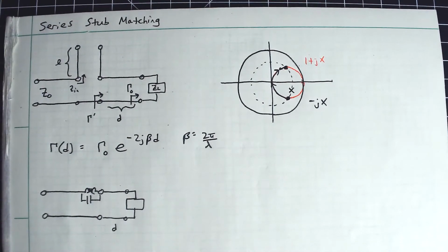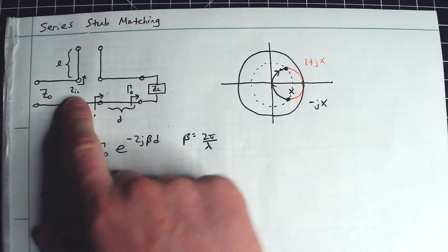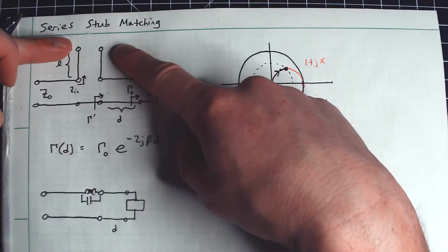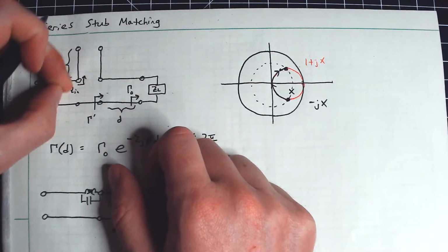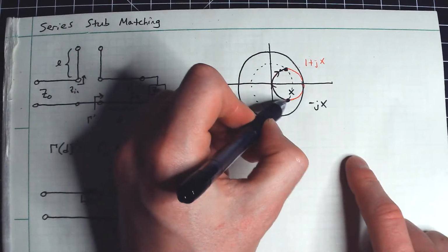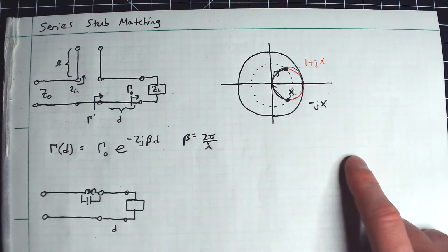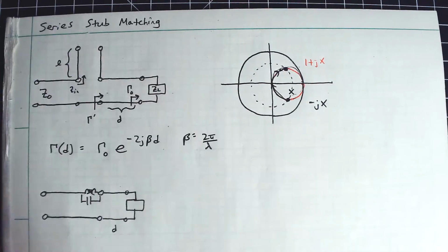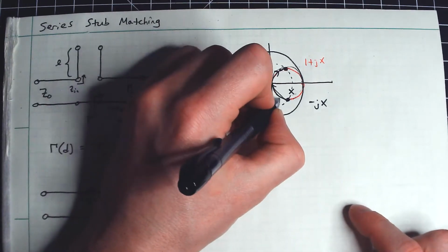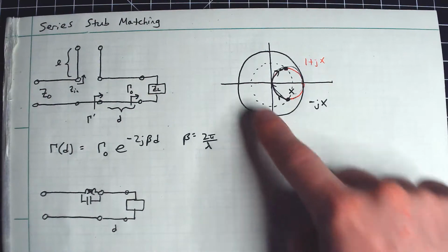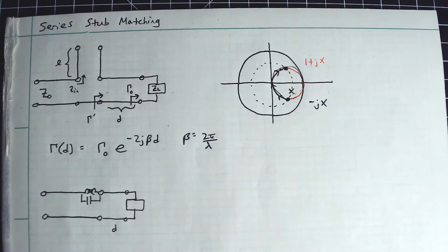down here. And that input impedance for an open circuit or a short circuit will be purely reactive. Okay, so as I dial L here, what happens is it just moves me along this circle, either one direction or the other, depending on what the signs will be. I believe, I don't know this off the top of my head, I believe it actually goes clockwise in this case. But we'll look that up and verify that later.